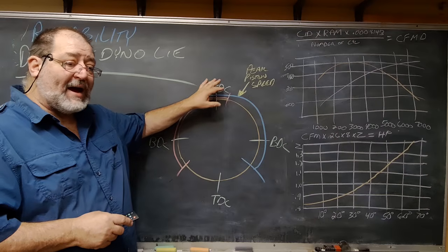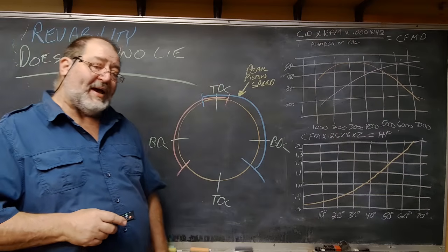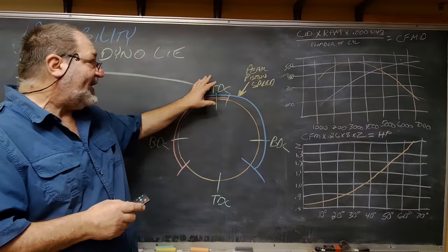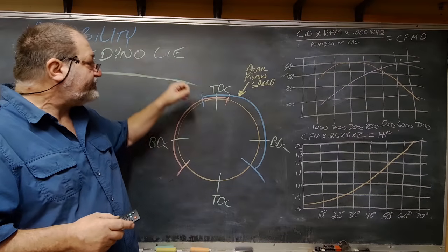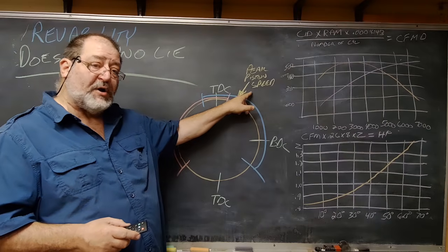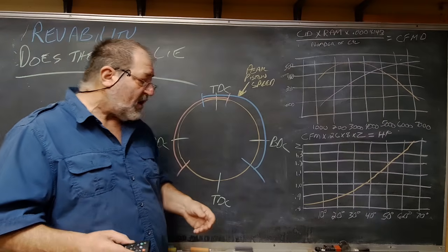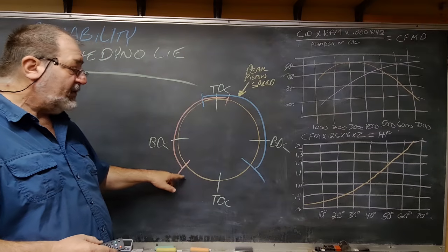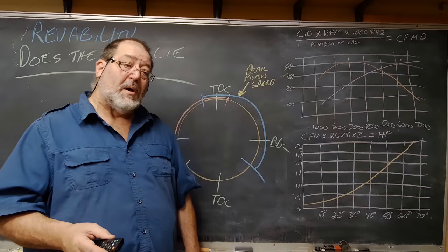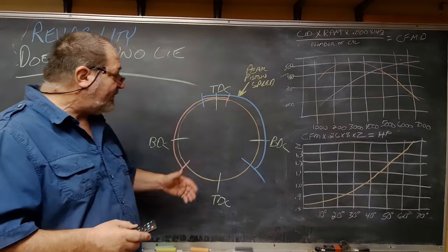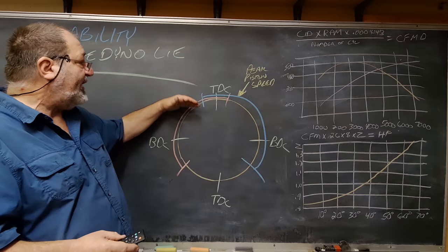Adding overlap without trying to make real use of it, of a tuned exhaust, is a bad idea. But you want that early opening because you want that better exposure. Same on the exhaust. You can push this out. This is your blowdown. It'll make it louder, but it'll make it rev better. It's about your breathing. It's about the piston not having to push out that exhaust.